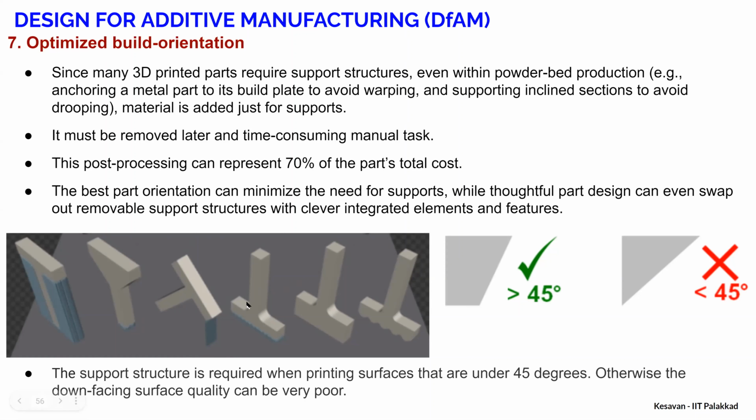Then you need to know some rules for the orientation. For example, if your component has an angle like this in the structure, if the angle is greater than 45 degrees, it doesn't require any support structure.